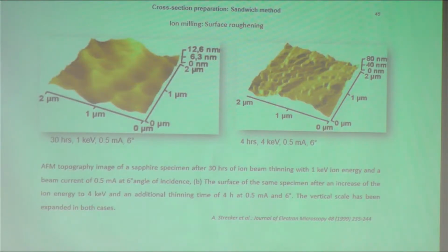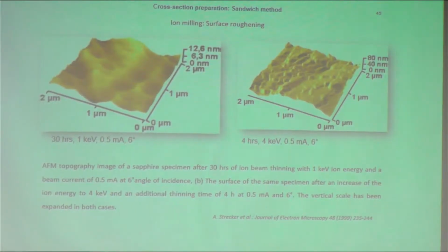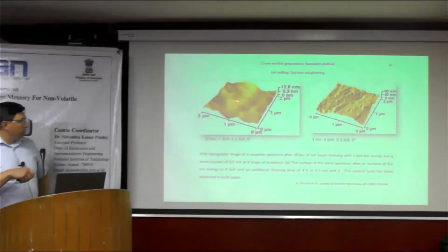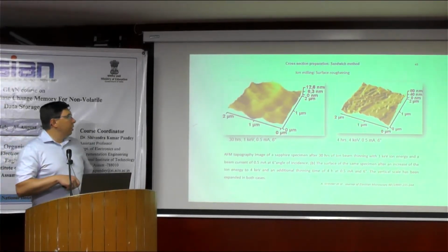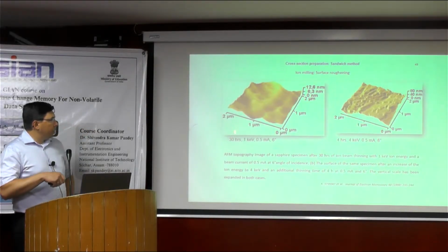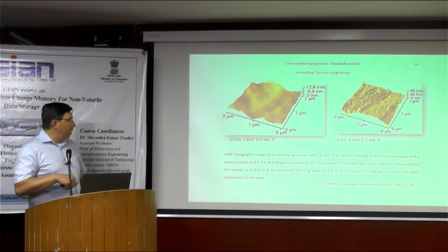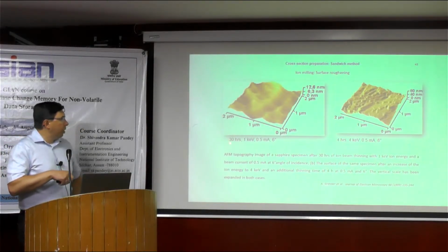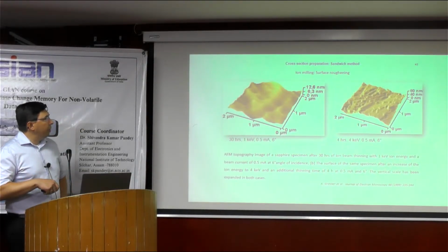So this image shows you the surface topography of sapphire. Here, after using ion beam milling for 30 hours at 1 kV, we get low roughness.